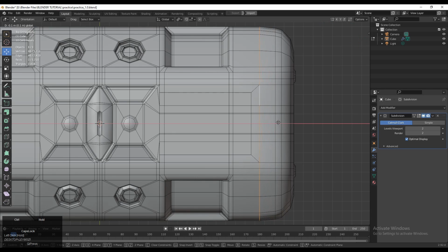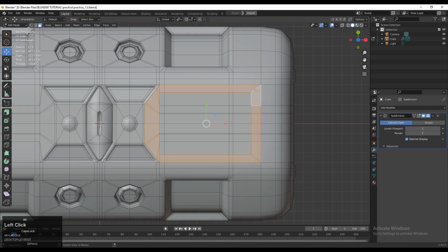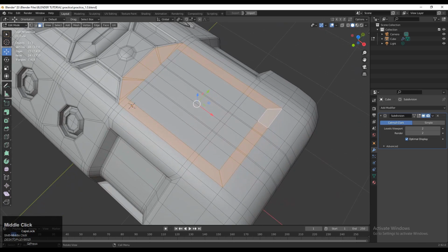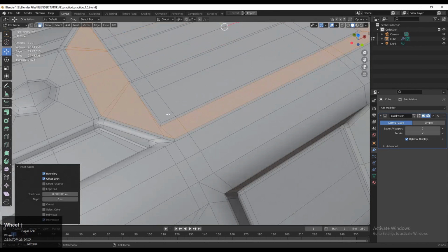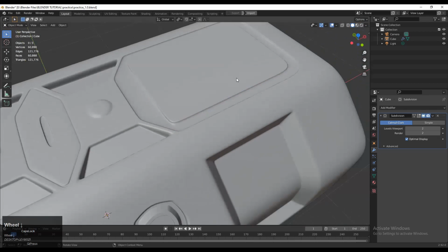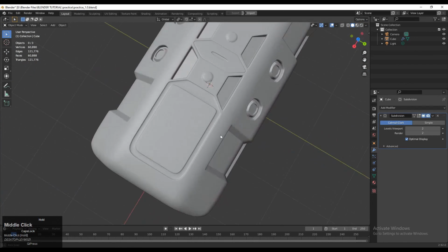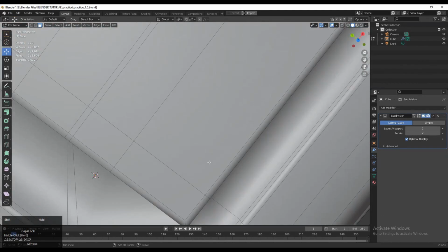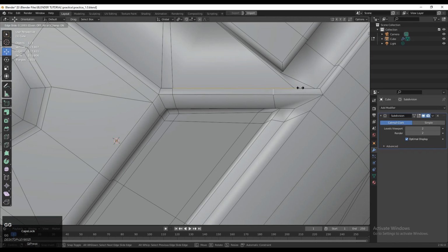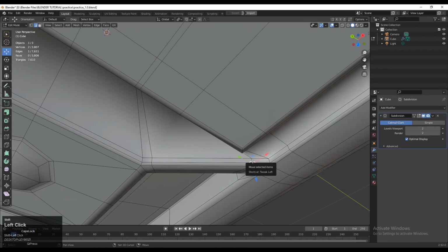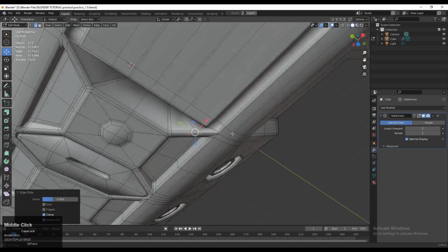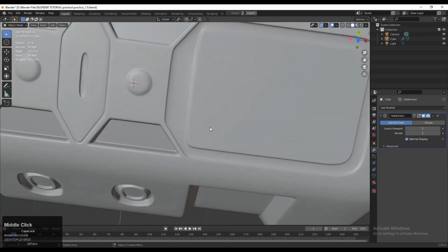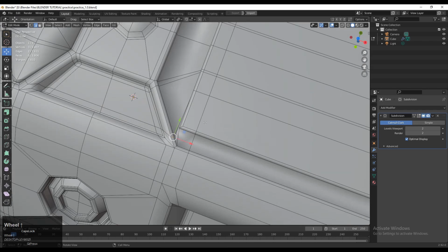So I can select this loop and then edge slide it, and now that loop will support the geometry and I will get the curve form to the side. Okay, now just use the insert operation here and then extrude it inside a little bit. And if there are any loop cuts, edge loops close to each other, then I can use the edge slide. So you can see that this edge loop is a little bit close to the others, so I can select this edge loop and then use the edge slide, double tap G for the edge slide. And that looks good, not bad.